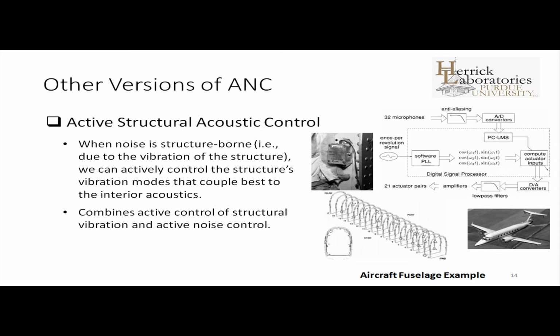The difficulty comes from something that I was talking about in the acoustic sources section. You may remember that the panel, if you've got a big panel, for example, no matter what its vibration is like, if you're at a frequency below the critical frequency, it doesn't radiate sound, whereas above the critical frequency it does. Okay, so that's a very simple situation.